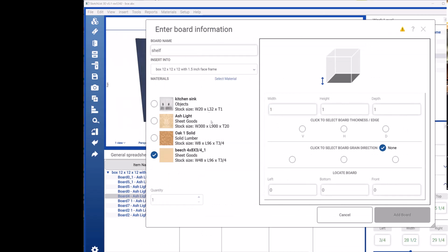So there's two pieces of information. What material is it going to be cut from? And you have to pay attention to the size of the material, because you can't cut a piece bigger than the material it's getting cut from. And Ed had mentioned before about the grain direction. Sometimes people will say, well, that really should fit. It's 60 inches and my board is 96 inches.